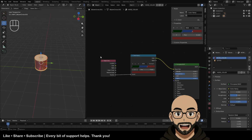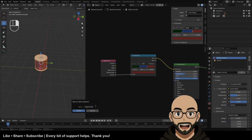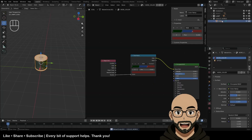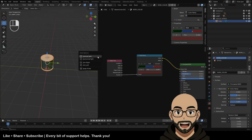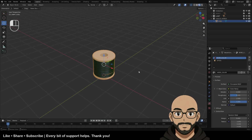Right now it's in the lamp collection. So I'm going to right click, move to new collection, and I'll call this coiled wires. Right, create a collection, there we go, and then I can call this coil, for example. I'm going to just join this back up. So right click this. I'm going to say join to the right. So we're back to our viewport.